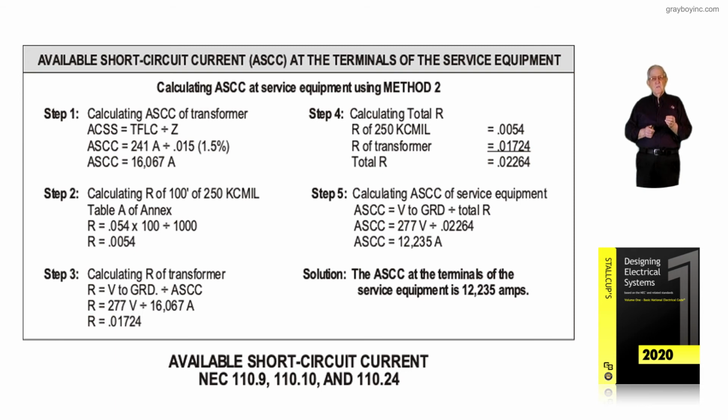But notice we're still using either a 15 KA system if you can purchase it. If not, you're using a 20,000 amp system or 20 KA system. And notice either method, you come up with about the same thing in the solution and the answer. But the people that I worked under, the engineers that I worked with, the electrical contractors I worked with, plan checkers and so forth, they all seemed to feel that this method 2 was the best method to use